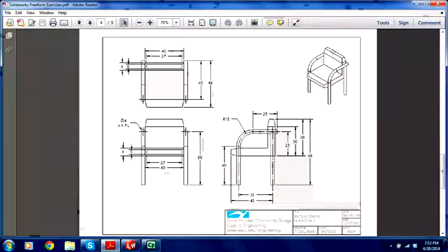What we'll do is this. We'll do the L shape first. We'll do 1 taper using a loft, and the second taper I will try doing a draft extrude to show 2 different ways, and hopefully one of them will work. Now once that's done, we will do the arms. I think the easiest way of doing the arms is probably just a simple sweep. So that's my plan. Let's start with the L shape, and I'm hoping I have all the dimensions.